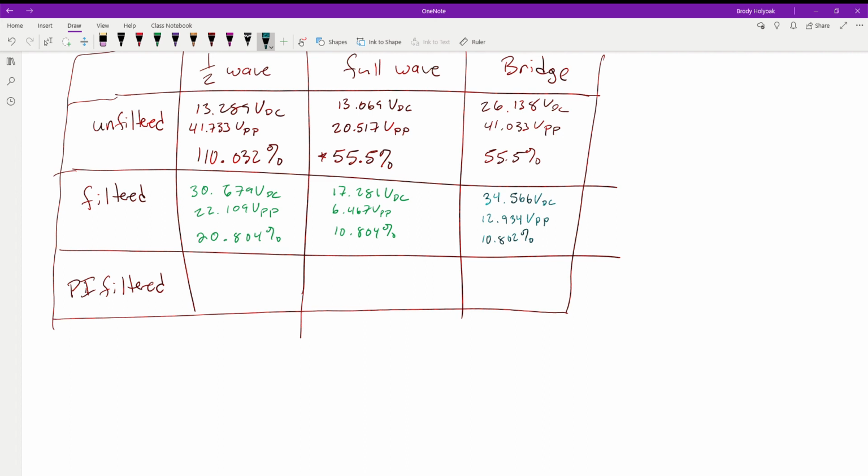So anyway, enough on that little side tangent, but just so you have an idea, these power supplies are very, very versatile depending on what output we want, and that's kind of the fun part on the last part of the semester with your labs, is figuring out what output do I want? So then I know that. Then based on that, what type of power supply do I need to build? And can I get away with filtered? Does it need to be super filtered like the Pi filter, or things like that?